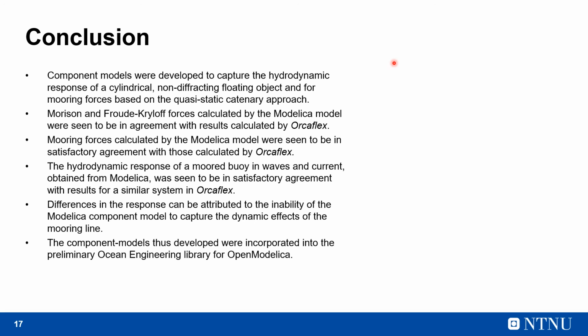The mooring forces calculated by the Modelica model were seen to be in satisfactory agreement with those calculated by Orcaflex. The hydrodynamic response of a moored buoy in waves and current obtained from Modelica was seen to be in satisfactory agreement with results for a similar system in Orcaflex. The difference in the responses, if any, can be attributed to the inability of the Modelica model to capture dynamic effects of the mooring line.